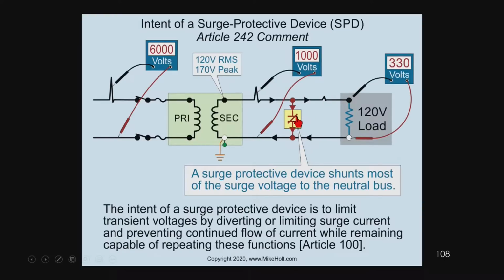Okay, so if you go over 330 volts, this device right here becomes a conductor, a dead short, let's just say. Well, if you make a dead short right here, what's going to happen to the current flow traveling between these 2 points right here? If this has a really low impedance, it's a short circuit effectively. Is the current going to get higher?